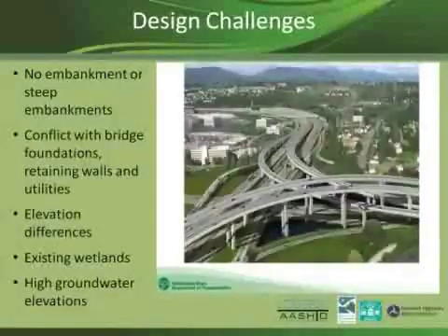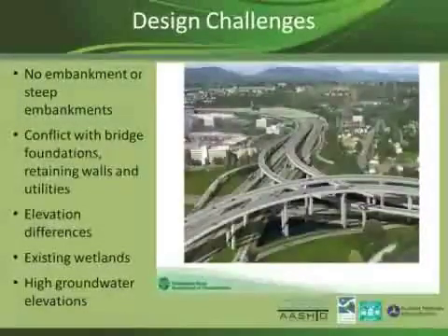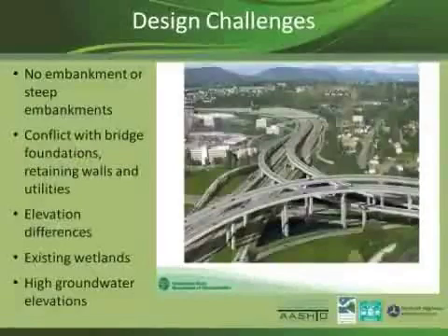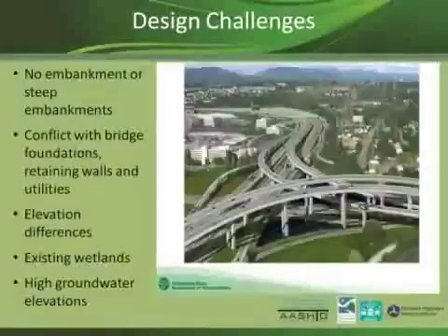Here, if you look at this, the challenge is more difficult to deal with in a highly urbanized area, an interchange area like this one right here. As you can see, multiple flyover ramps cross one another, so there's no good place to put a treatment BMP anywhere. There's no embankment next to the structure here, so we cannot really put an ecology embankment or stormwater wetland here. At some locations it's not like this, and we have a really flat highway, and we are facing another issue: sometimes we have an existing wetland on both sides of the freeway. And then